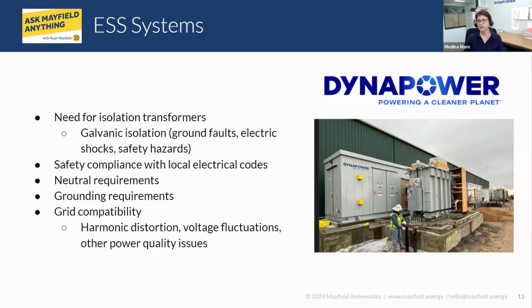Grounding, flexibility to ground the system, because some of the utilities will require Y connection or Delta connection if they have grounding issues, and if the utility side is grounded, then they will require Y connection that will be grounded. That Y connection and grounding can also create a lot of issues on a PV side.